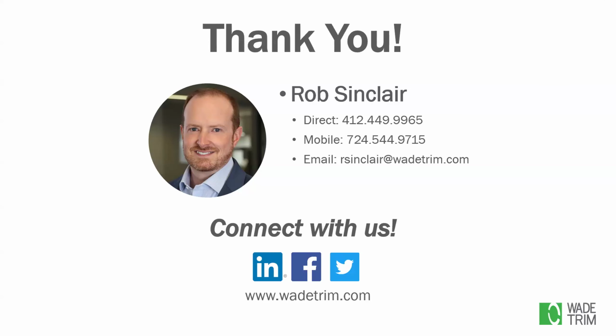You were also talking about bringing in large aerial imagery. The question was asked, does Nearmap create SID files? I don't recall off the top of my head. I don't think they do. I think they're JPEG or TIFF, so you would have to download that and then convert it in GeoExpress. GeoExpress owns the rights to that SID format, so I think they're the only software vendor that will allow you to convert it.